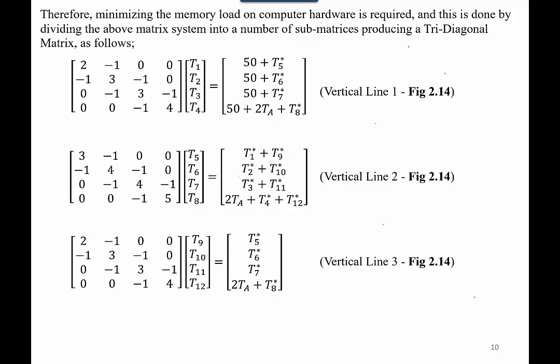If we take this maximum value of residual 0.1 centigrade, maybe you will reach 13 iterations, or if you choose another number, 0.01 degree centigrade, maybe you will end with 200 iterations. So it depends.